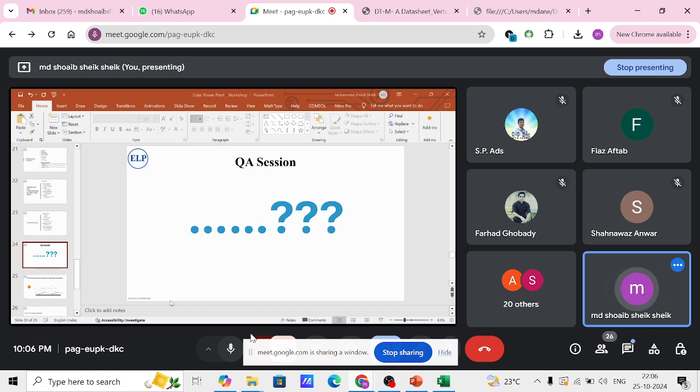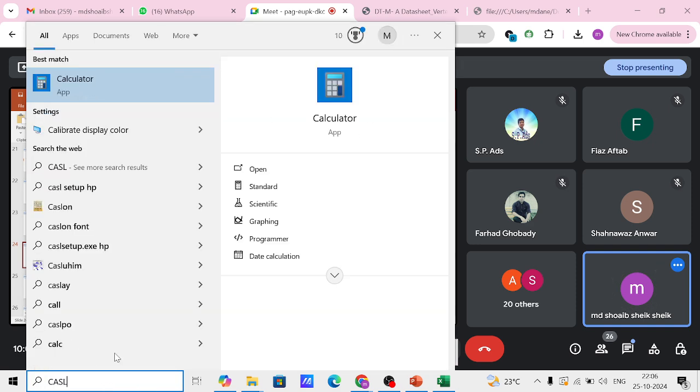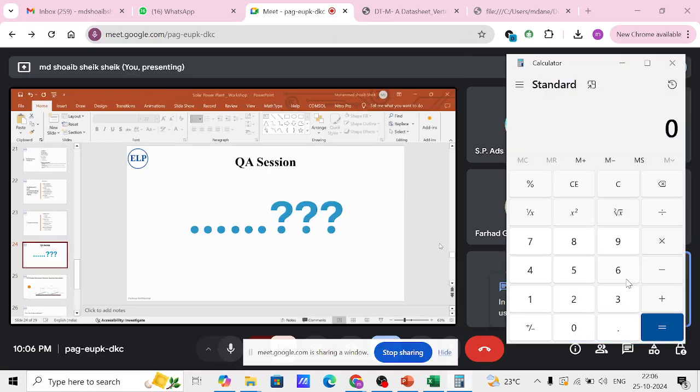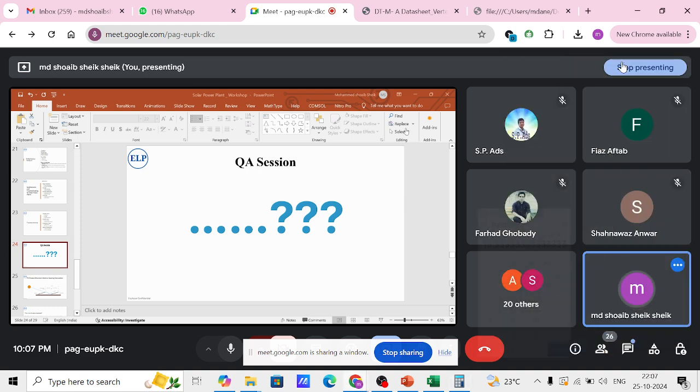Let me calculate that: 600 volt input for the MPPT of that inverter, and 45 volts per panel. So you can utilize 10 solar panels in a single string in series connection.